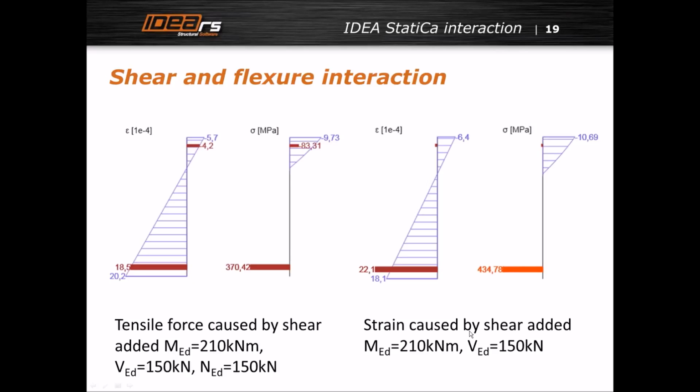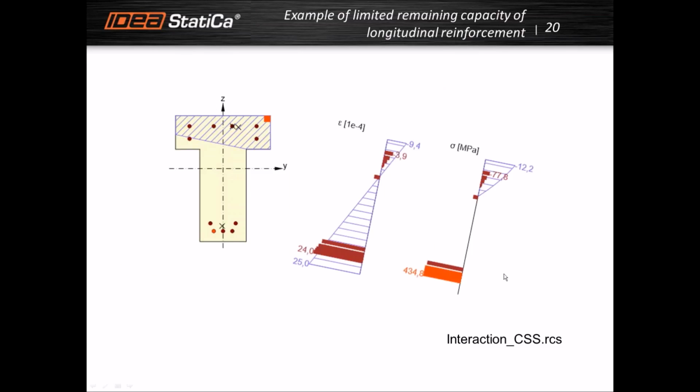Then we calculate the response and we check the total strain against the limit value, and also the stress is calculated and checked, with respect to the stress-strain diagram, so it is non-linear. We believe that the procedure is a reasonable interpretation of the variable angle truss model, even if we know that it is not a calculation of virtual reality.